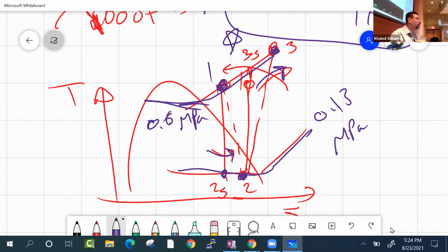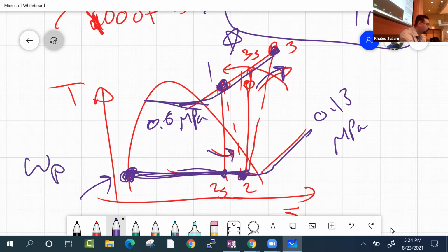So to do a cycle, we cannot just go up again. What do people do? They condense the water vapor all the way to become saturated liquid, in a condenser. Why? Because water can be pumped so efficiently, so cheaply. The energy of the pump that will take you from the same pressure to that pressure is very tiny. It's only this much, and that's an exaggeration.